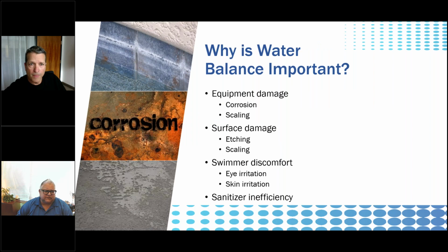So I want to start with just a quick recap or refresh of why water balance in general is important. And specifically, why is pH so important? pH is an issue in saltwater pools simply due to the nature of how we break apart the salt molecule and turn it into active chlorine. I'm going to show you an equation here in a minute that explains that. But ultimately, keeping pH in balance is a very important part of pool care.